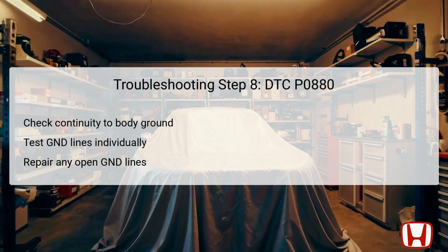And if all previous steps checked out, the TCM may need replacement. However, if there is no continuity, it signifies that an open circuit exists in the GND lines, which must either be repaired, or ensure that ground connection G101 is secure and without corrosion or loose connections. Proper grounding is critical for TCM's operation since it ensures that electrical components function correctly without interference from unstable signals.